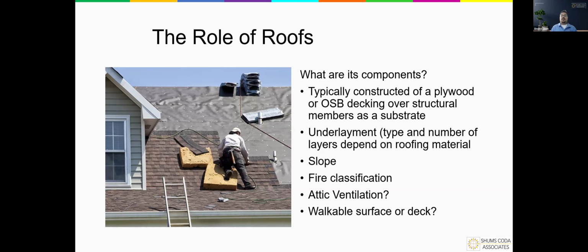The flatter a roof is, the harder it is for air to pass from a low to a high point. It also changes some of the materials that are allowed, a lot of whom are a lot more sealing in nature. That's going to be things like your PVC roofs, your TPO, your EPDM. You have a number of different options there, but then it's also important to discuss that and right-size that for what implications that is going to have on the way that we plan this attack with our design and our attic ventilation and what code sections are going to apply.